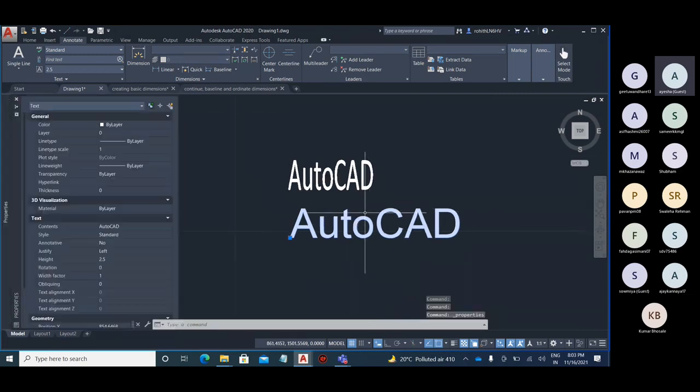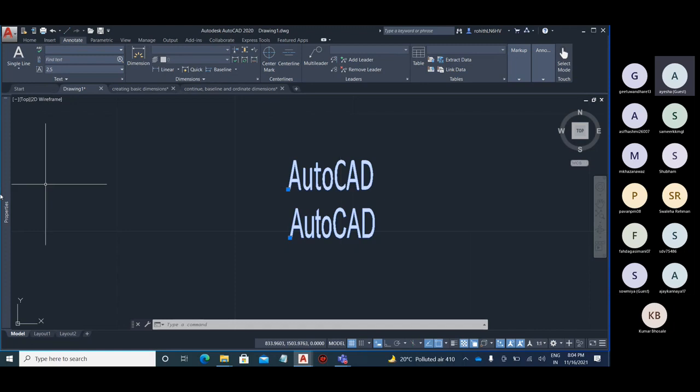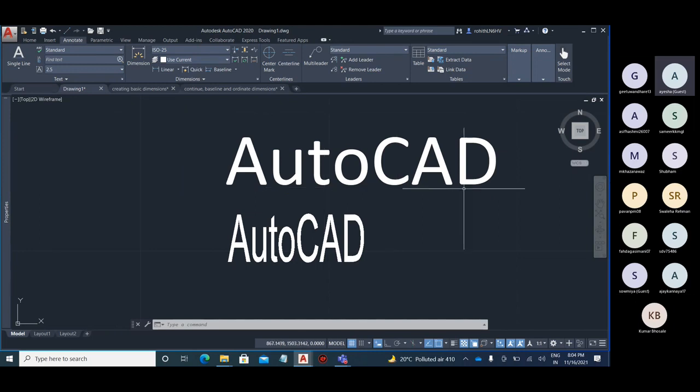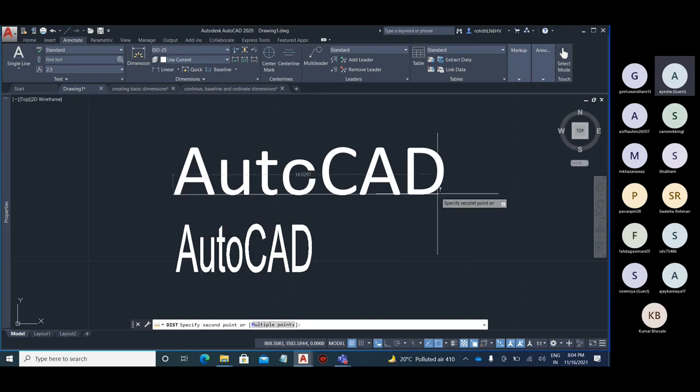I can change the width factor of this also individually. So get your properties panel, and in this we have a width factor. If I want this to be 0.5, you can see it has been reduced to 0.5. What is a width factor? Width factor is how much width the text will take. If I give DI and measure from this point to this point, what is the distance? This is an approximate distance, let's say 15.